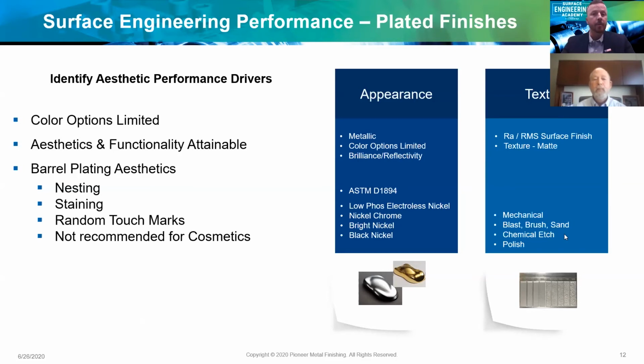I'll also take this opportunity to point out again the barrel plating process here relative to aesthetics. Not recommended, quite frankly. Now, there are certain applications, small, say, commodity type shapes of parts that you can get away with barrel plating and still produce a cosmetic finish. There's really no way to predict where touch marks or any sort of potential shadowing or shielding of the electric current could take place. Obviously, have less of that in the electrolysis process, but still a high propensity for staining, a high propensity of having touch marks in places or critical surfaces that they're not meant to be.